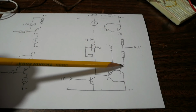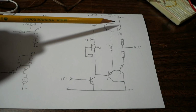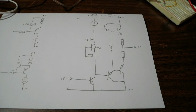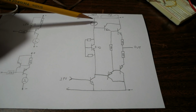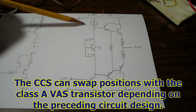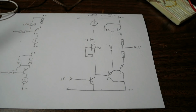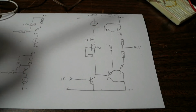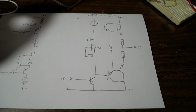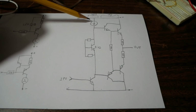Also, as these transistors heat up during use, you want this to thermally track that and keep that bias relatively constant. And now the third and final function of the VAS stage is the constant current source. Arguably not as important as these two. I mean, you could just replace it with a resistor. However, in a hi-fi amplifier, you don't really want to do that. And this is mainly what this video is about, the constant current source, and we'll take a look at a couple of them and see which one will work the best.